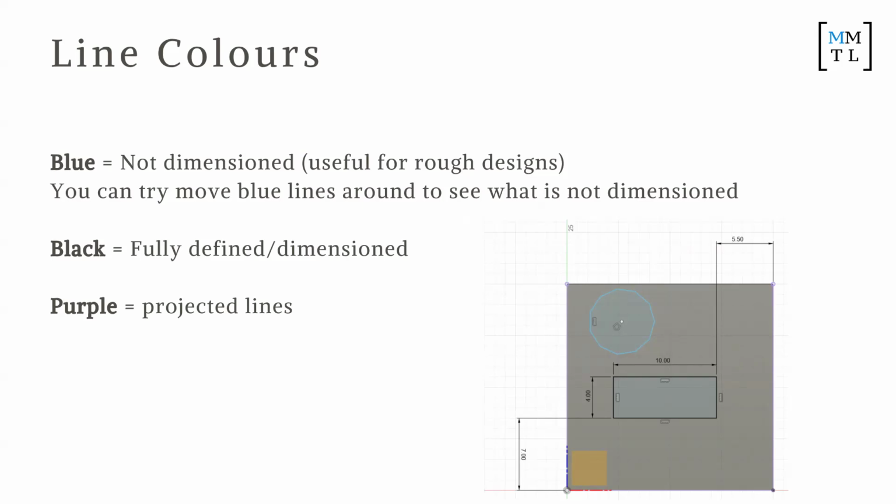If you have an orange dotted line, that just means you've made a construction line. Click on that line, and then in the sketch palette there'll be a line type option. Just unclick construction. If you see orange lines, you really can't operate with them, so make sure you aren't creating this beautiful sketch of orange lines and then realizing that you can't use any of it later.